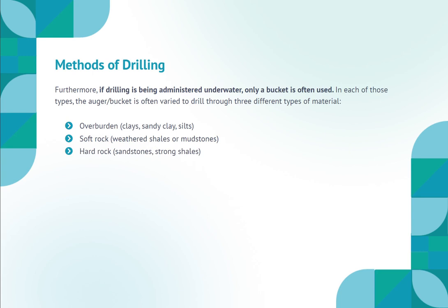In each of these types, the auger or bucket can be varied to drill through 3 different types of material. Overburden: clays, sandy clay, silts. Soft rock: weathered shales or mudstones. Hard rock: sandstones, strong shales.